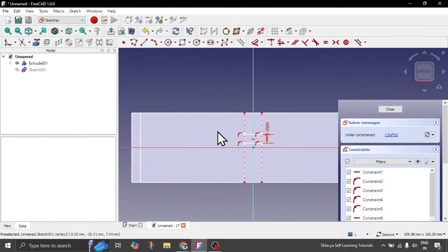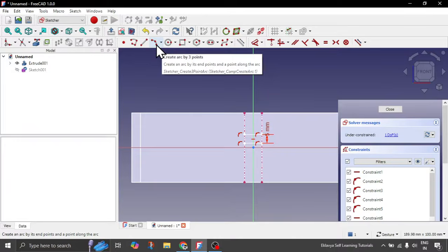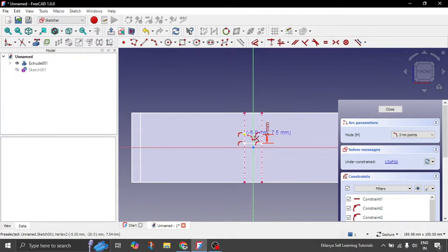Now let's draw something on left hand side, the eyeglasses basically. You can use B-spline if in case again you want, or you can use your arc basically. Click on this point. Sorry, let's create again. Click on this point, click on the end point where you want, and something like this. Here also you can get decent curve, but if in case you want something more precise, you can definitely use B-spline. So let's make it, I think, better only for your guys' reference, right? So this one we can keep like this.